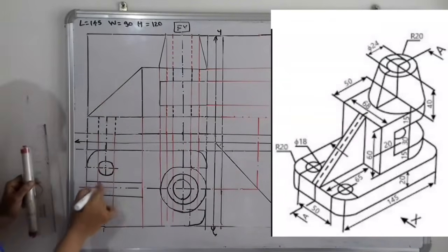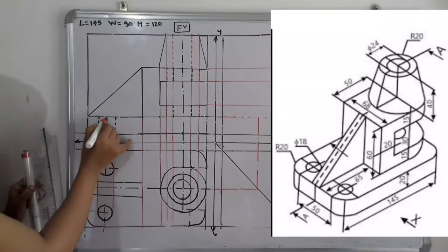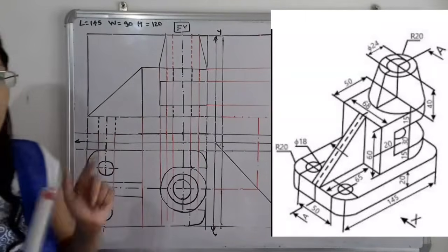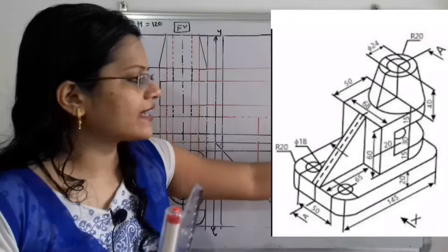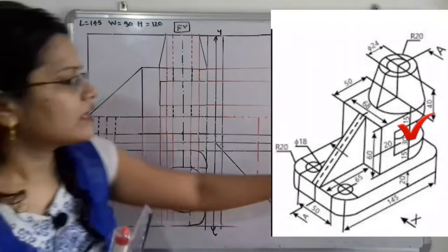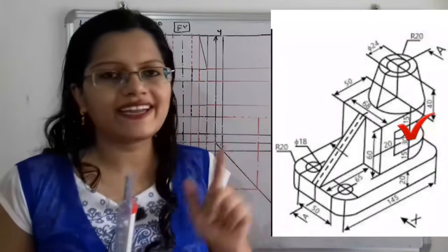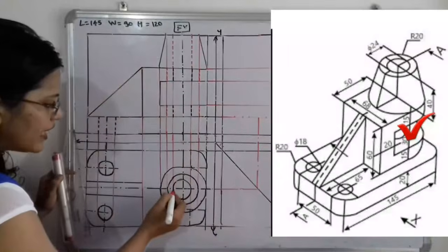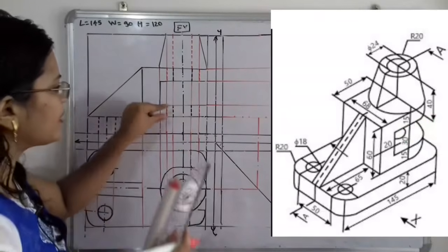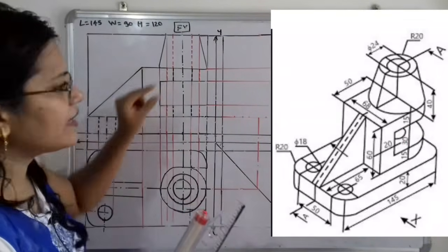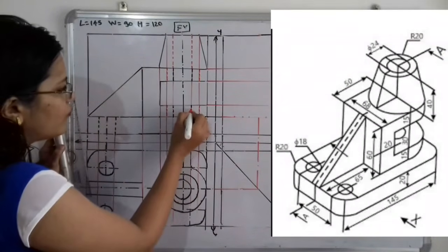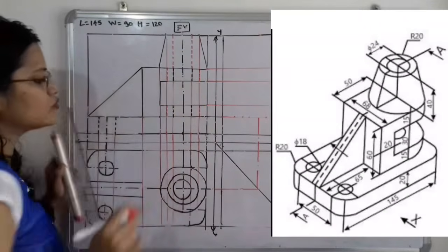We have to project the center, that is the line passing through the center, in the form of dash and dot, and here in the form of dash we have to show the holes. Now in the same way, if we observe this diagram, for the construction area that has this L shape, there is a small hole that can be seen. So this small hole we can project from the top view to the front view. This construction has a height of 15 millimeter, and the hole exists only for this construction. So we have to draw it here in the form of dash. So we have to show these two holes.